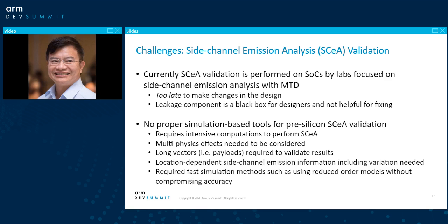So currently, for side channel security simulation in the market, there's almost no solution. And if you want to do simulation based for security, there are a lot of challenges. First, you have to be able to run long vectors, which means thousands or millions of payloads. And then you need to have a very accurate solution. And also the sampling points in the time domain need to achieve maybe 10 sampling points or up to 60 sampling points in each cycle. So it's a big challenge.